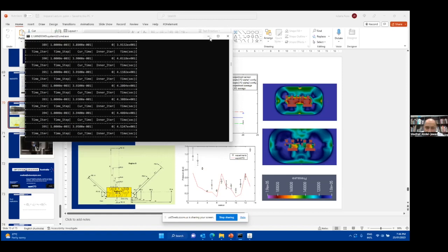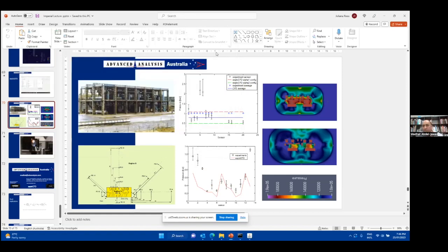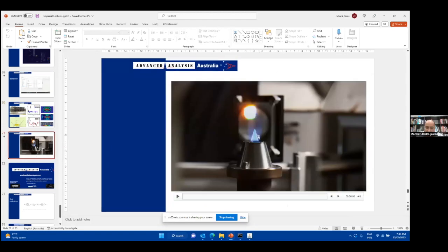We said that the turbulence from pipes and cross flow can cause instabilities in flames that increase the speed of the flame, which results in higher overpressure. But it's not just that. There's a whole series of instabilities, Rayleigh-Taylor instabilities, and one interesting one here, and this comes from an experiment at École Centrale, is the effect of sound. Just sound can affect the flame.